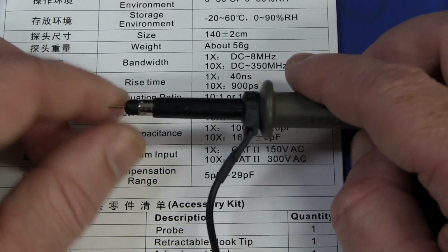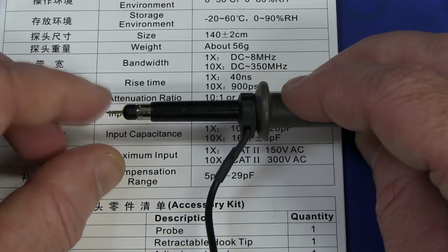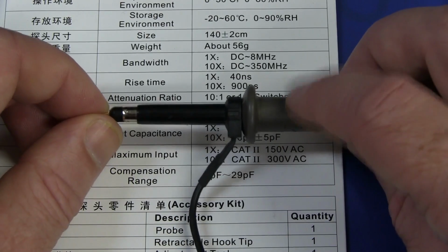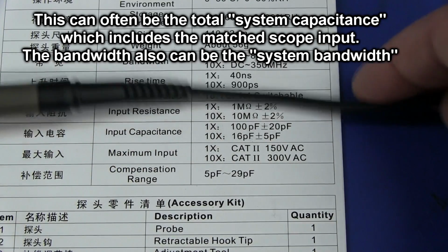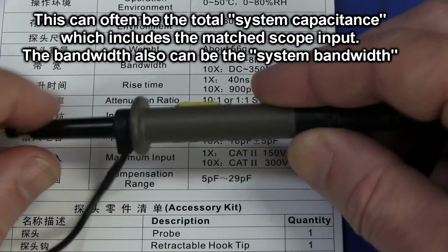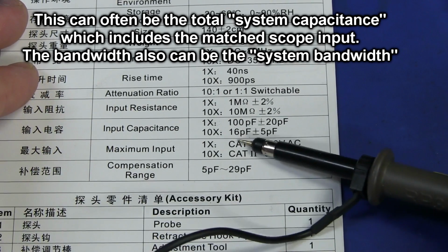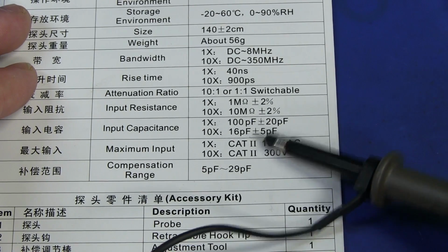And I say the word effective because it not only includes the small amount of capacitance between your tip here and your input compensation network in here, you start your 9 meg resistor down in there, but it's also the effective reflected capacitance from your coax as well. So it's that 100 picofarads, but because we've got a times 10 divider in there, that capacitance gets divided down and then becomes effectively 10 times less at your tip. So that's why that one's 10 times less.